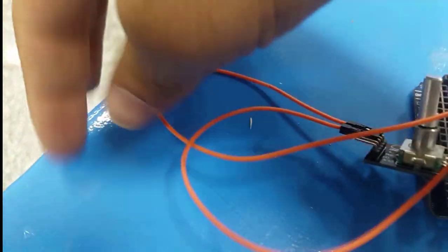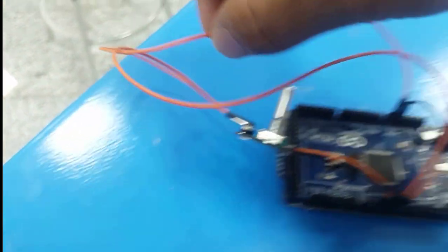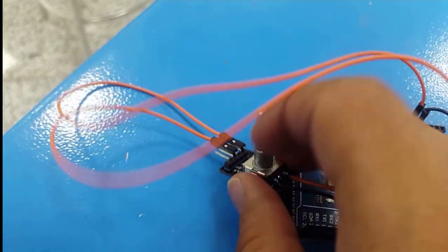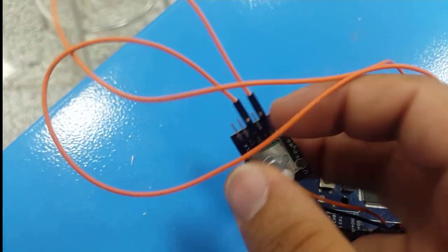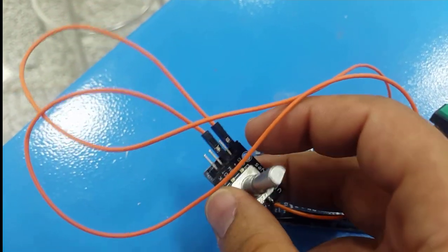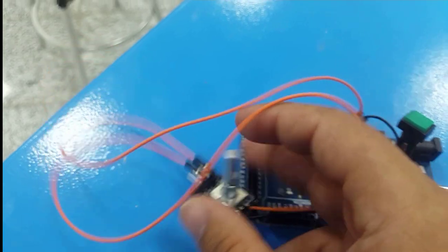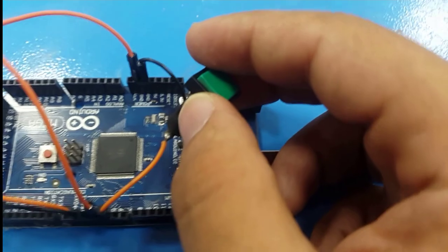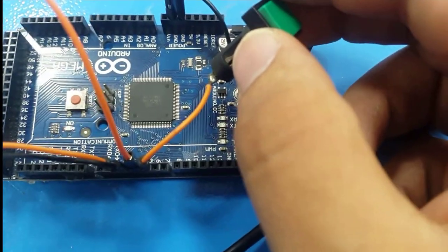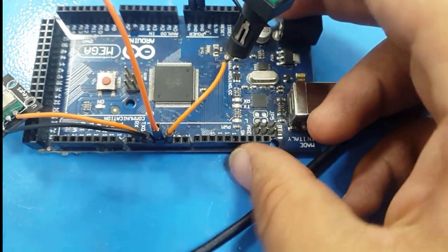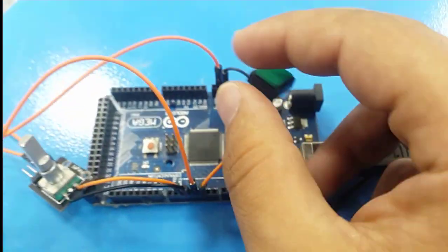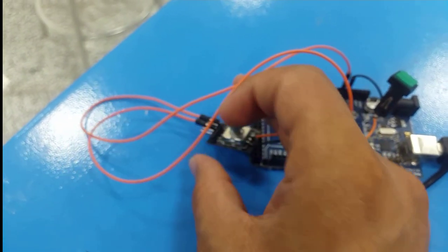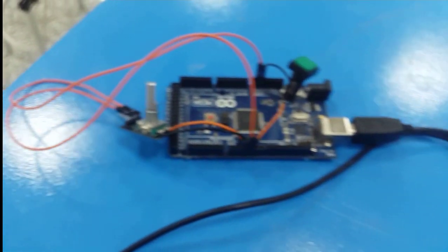I connected the ground wire, which is this one, to the ground wire of the Arduino, and I connected the switch for the heading engagement and disengagement of the board to the SW pin of this module, and I also connected a push button here between the pin ground and pin 5, I guess. Yes, pin 5. This one is for autopilot engage and disengage. This one is the rotary encoder, and pressing that will engage and disengage the heading for us.